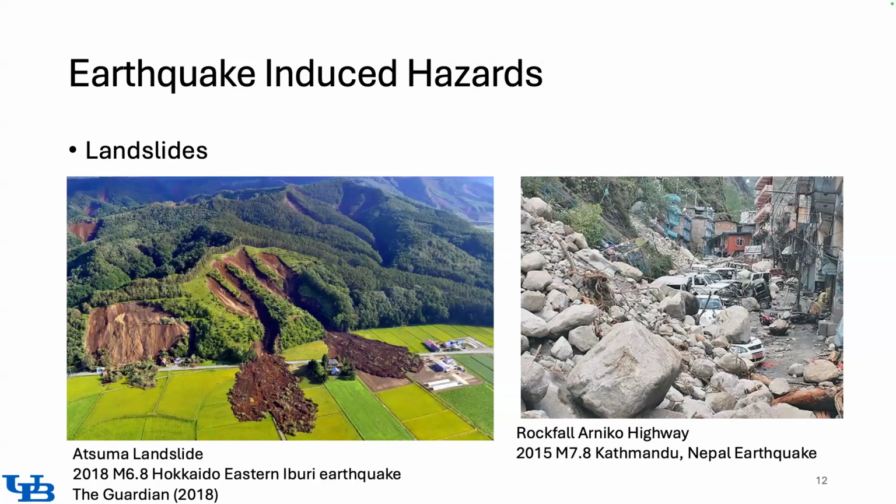Landslides are also a fairly frequent hazard produced by earthquakes. And again, for two reasons: the additional loading that a slope may experience, causing it to fail, especially if, under static forces, it's already very close to the shear strength imposed, but also because the material is relaxing. And also in areas where you have rock outcrops, you can have rock falls, which again may have devastating effects.